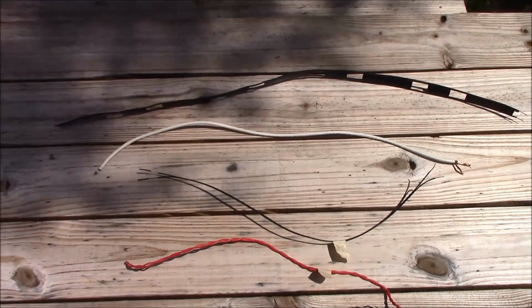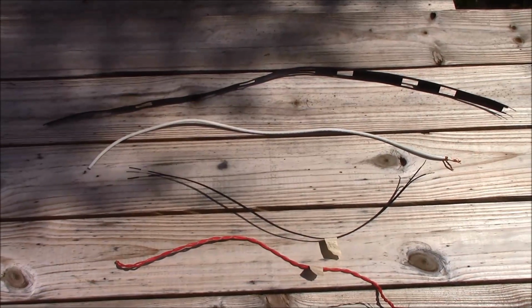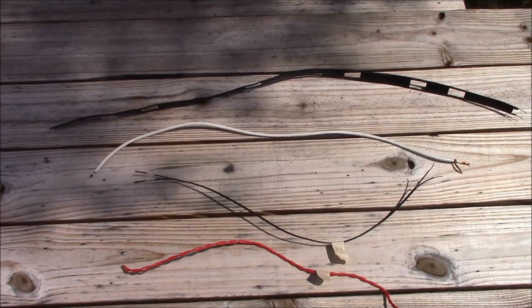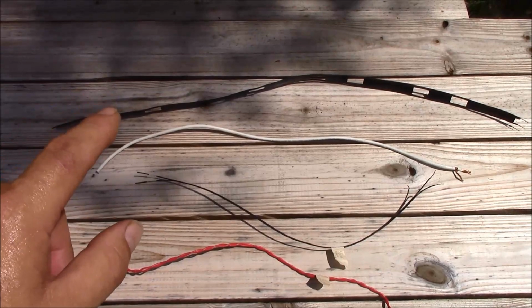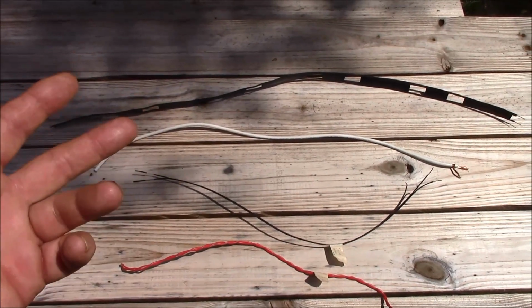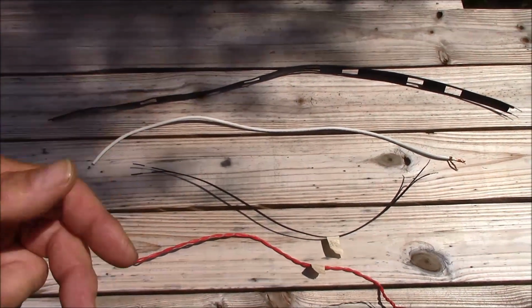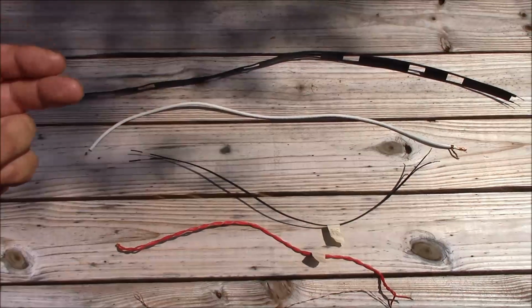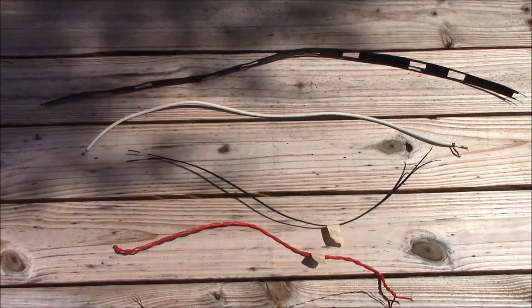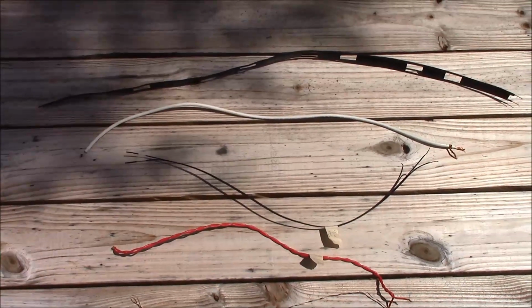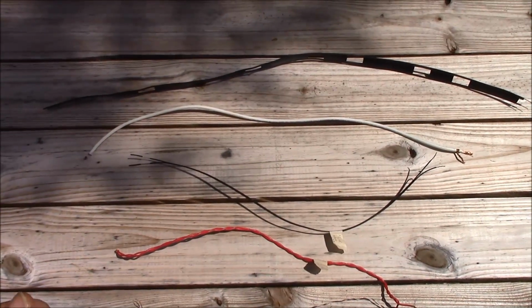That line on top is a 450 ohm feeder. If we are very careful to cut that feed line to even integer quarter wavelengths, like a half wavelength, a full wavelength, et cetera, it's a closer match to our equipment, and our equipment is actually going to transfer its power more efficiently to the load that we've built.